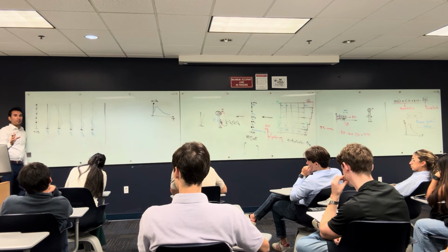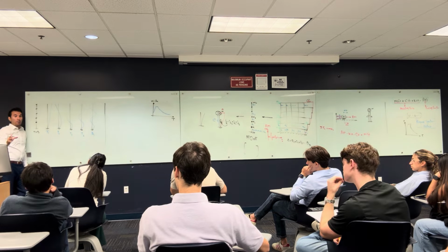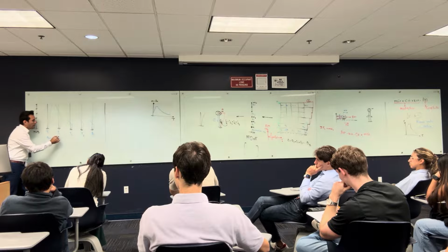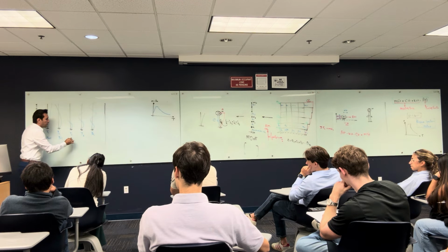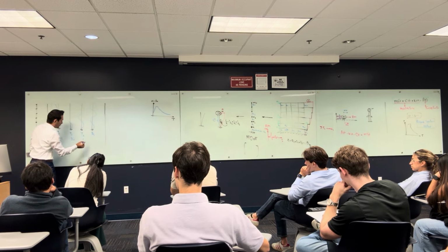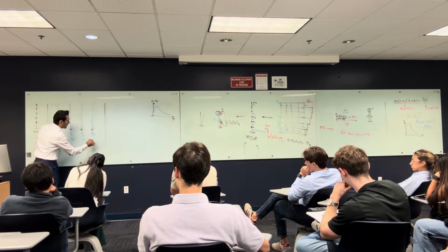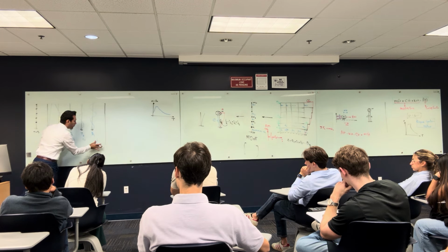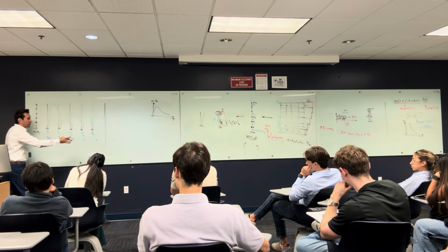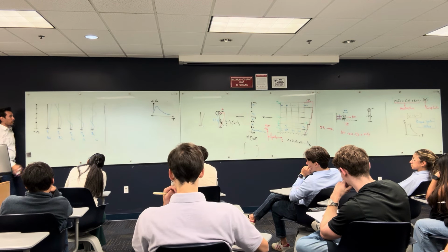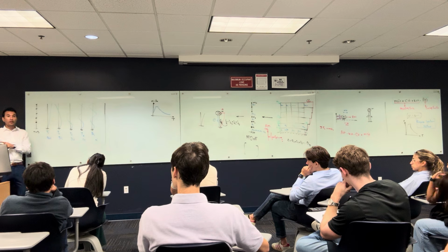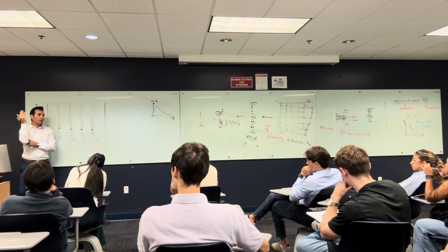And this depends on something called the mass participation factor. Most of the mass makes that movement, and maybe I would say 90% of the movement is that movement. And maybe you have 5% that movement, 3% that movement, 1% that movement, and let's say 0.05% that movement, and maybe other movement, whatever. To complete the 100%, I'm gonna put 1. So with 1% of the movement that way, you barely can see it because most of the movement is coming from this one. That is the first. And by the way, this is only in one direction. In the other direction, you are gonna have other mode shapes.